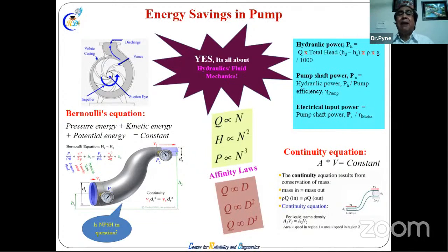Energy saving is not nothing but purchasing some energy product or a VFD and putting it in. Even if you put the VFD, if people are not taking care of these things in operation, you will never get savings, and people will curse you. They say, what happened? I purchased all this, I changed the VFD, why am I not getting the savings? So we have to take care of what the VFD-driven machine is doing.